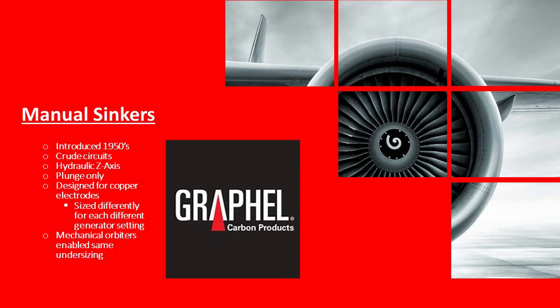These early machines, 1950s into the 1960s, had pretty crude circuits, a lot of arcing and pitting. The operator basically had to know what he was doing by changing settings on the control and stand there at the machine to make sure things didn't go badly. Most of those machines ran hydraulic Z-axes, which were extremely accurate. They used a hysteresis system for balancing the Z-axis and holding it in position. They were only plunge-style machines back then.